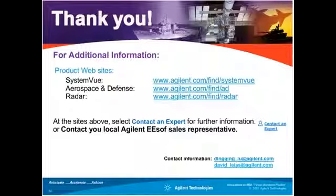Start from there, you can see we specify 2 targets in the design, and each target can be specified the position, the speed, and the distance. And in the transmitter, we specified 2 sub-array structure to point to different areas to do the searching and the detection model. So you can extend a little bit of this. For example, if you want 4 targets, you just copy-paste this, and you specify different parameters, let the targets be in different positions. And on the transmitter side, you can copy-paste it to do the full sub-array system to point at different regions. Finally, you finish your multi-target detection. Thank you. Okay, thank you.